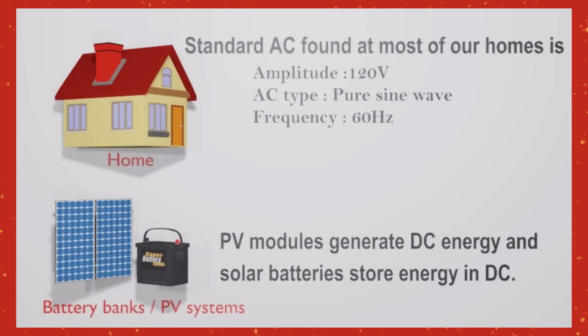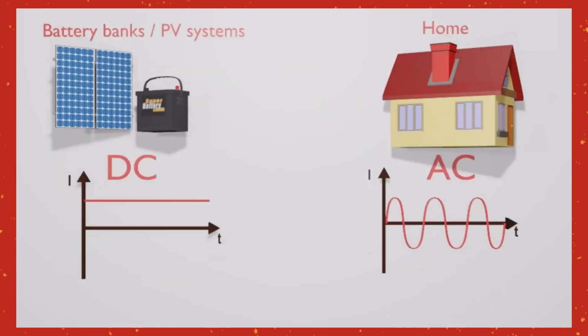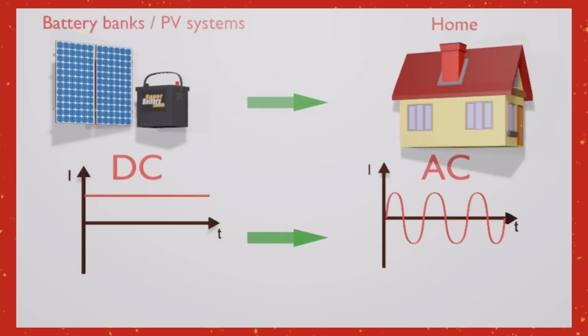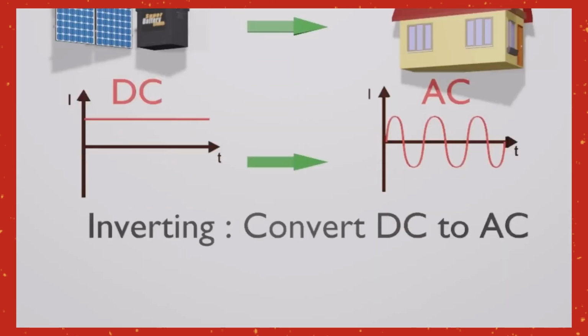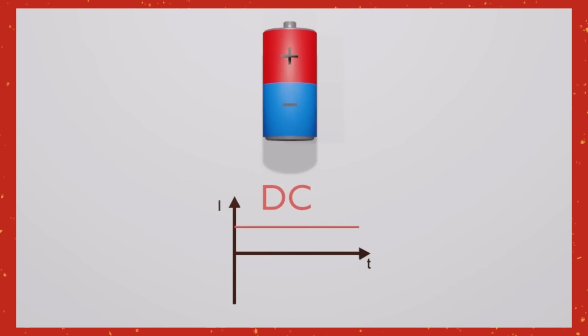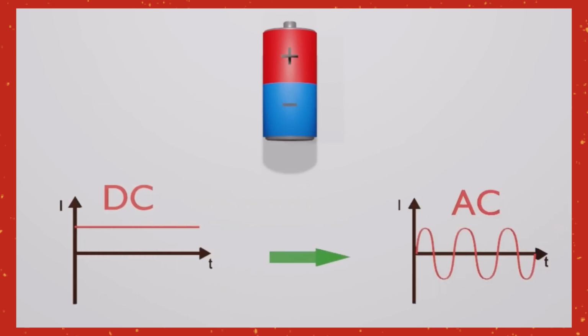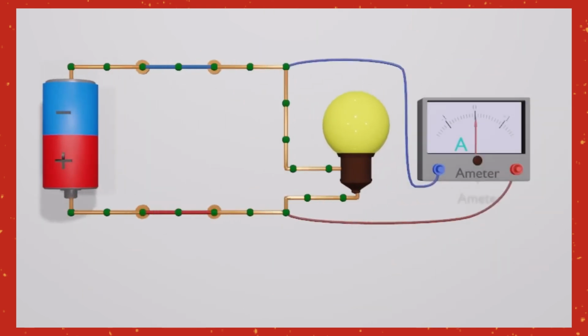If all the current you produce flows out in one direction, what about disconnecting the wires? The current becomes zero. Then, let's flip it back. Now we have current that flows in the opposite direction. Likewise, we can change the wires back and forth, so the current direction keeps reversing. What you end up with is very abrupt changes of current. All in one direction, all in the other direction, and back again. Look at the graph of the current against time. You'll get a square wave.